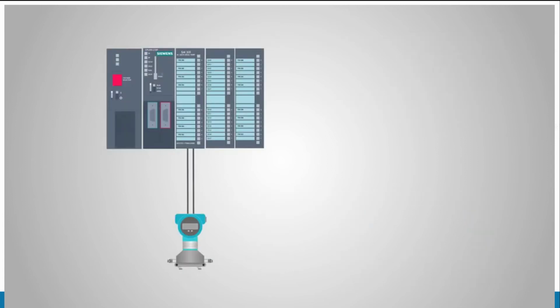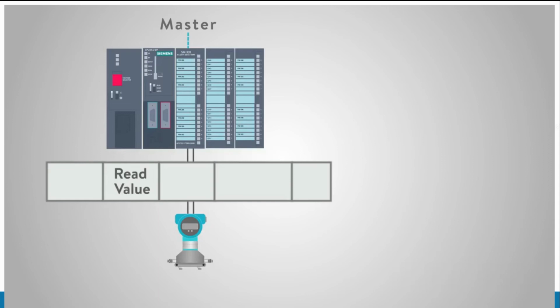accessible. Data from a Hart sensor must be requested by the master node, which controls all conversations on the loop. The master node is typically the DCS or PLC analog input card that the sensor is wired to. Each message from the master includes the request type, such as send measurement value, the node number of the sensor the message is intended for, and any data that needs to be transmitted to the sensor, like a new value for the upper range limit.